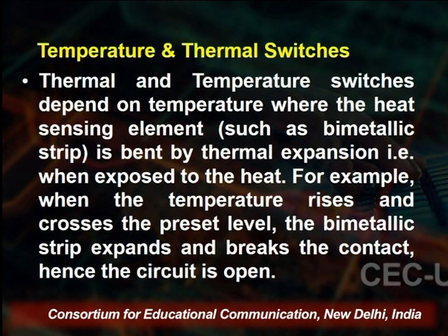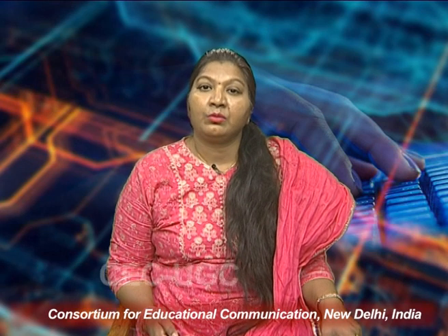Next type of switches are the temperature and thermal switches. What are temperature and thermal switches? Thermal and temperature switches depend on the temperature, where a heat sensing element such as a bimetallic strip is bent by thermal expansion when exposed to heat.